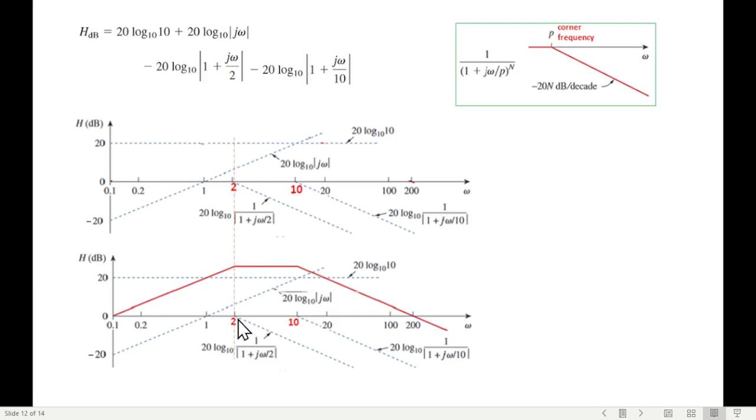Now what is happening here is that there is another curve going down with the same slope, 20 dB down. Now this positive slope and this negative slope will cancel here. So what will be left is only the straight line. So our result will be a straight line up to the next change.